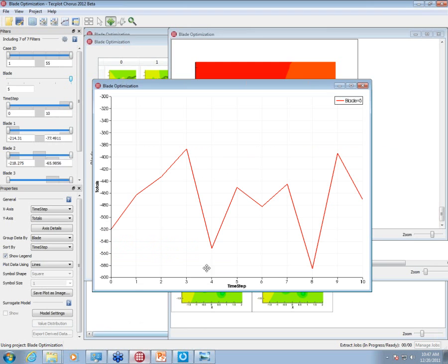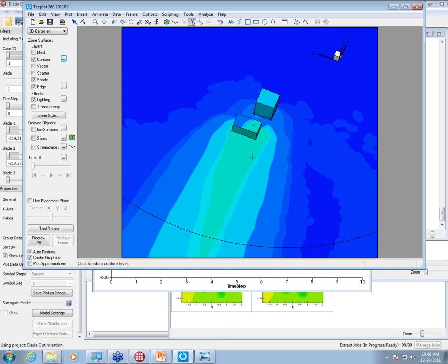A style file, which is what Tecplot 360 saves out, includes the information about the style necessary to create the plot. Because it's a text file, you can actually edit it if you had a set of contours you wanted to put in. But it's maintained across. The contour levels are in the style file.